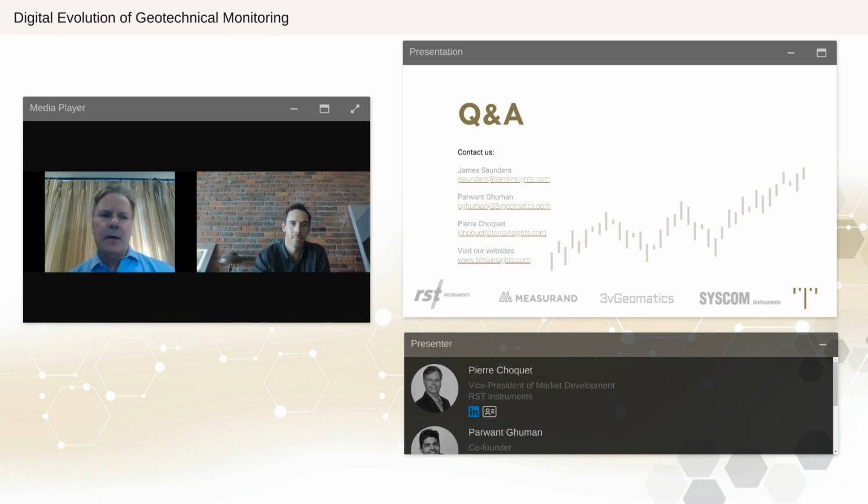But they have a spec also of a stability of the horizontal movement, the detection, if you will, of an IPI over a length of 30 meters. I think they spec plus or minus 2 millimeters over a string of 30 meters. Our spec is 0.5 millimeter over 30 meters. So we're much better than the ISO spec.